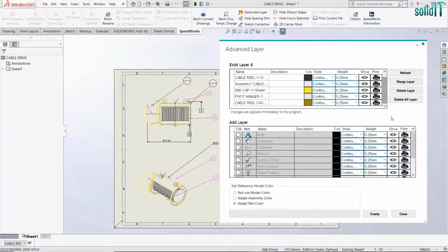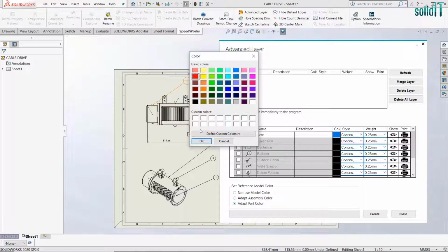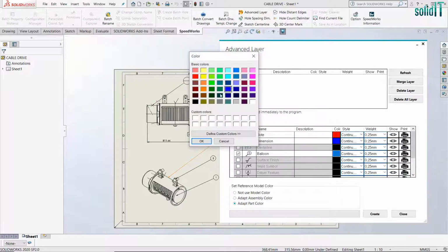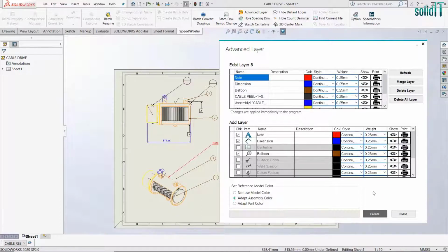Changing layers of a drawing that has already been created is a hassle. Selecting and changing lots of dimensions and annotations is simple but takes a lot of time. Advanced Layer allows you to modify layers of dimensions, center lines, and knots, and eventually reduces workload. In addition, you can create visually clear drawings by assigning the prime color of a model as a layer.